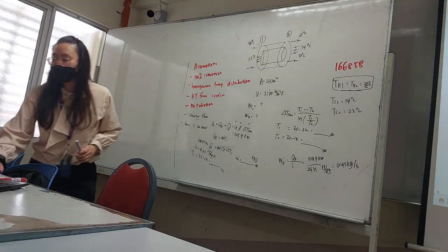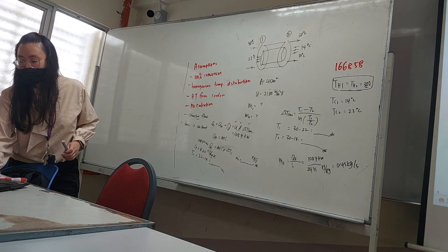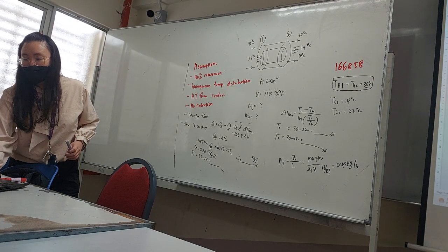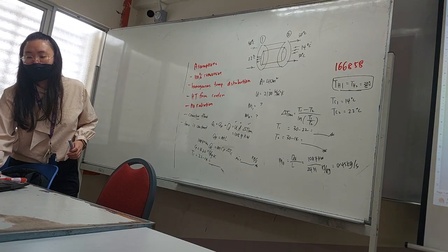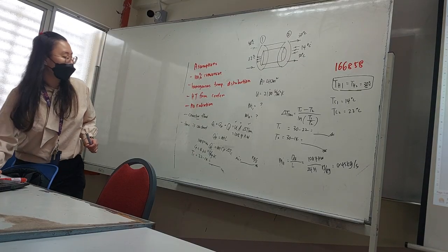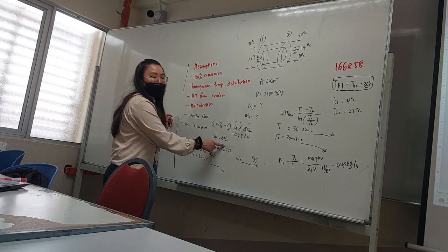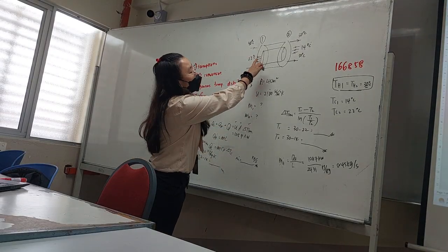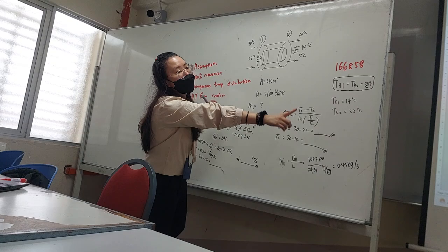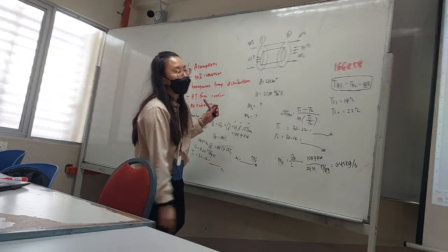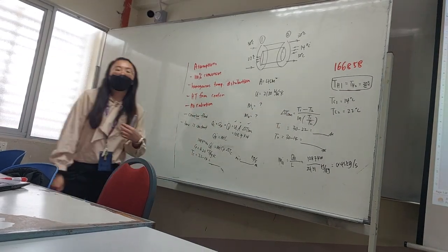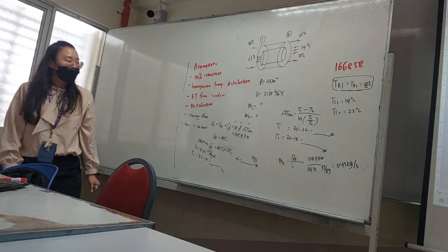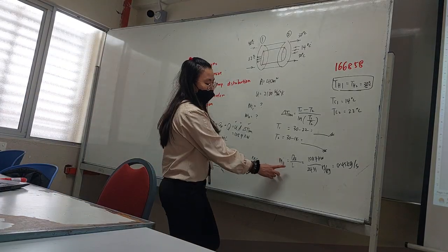You need to find two mass flow rates. So one is for the cool water, because there is no phase change. Second, the steam, they said, is a rate of condensation, meaning that it undergoes a phase change. It's a condensation process. So that's why Q equals mL.